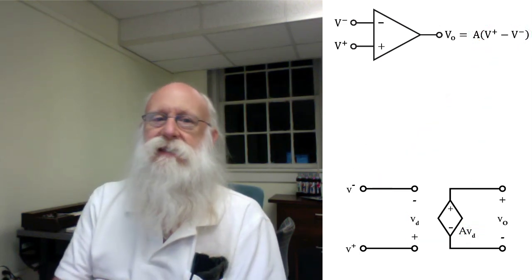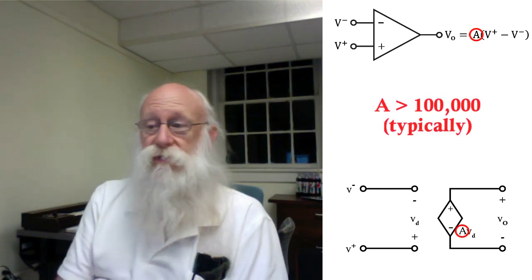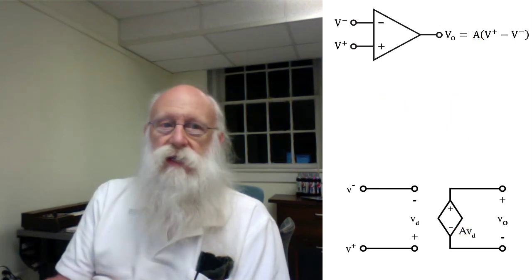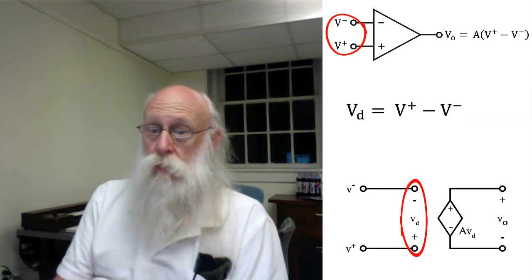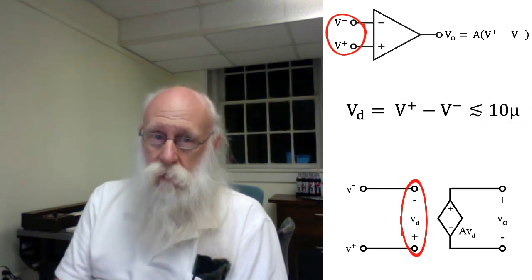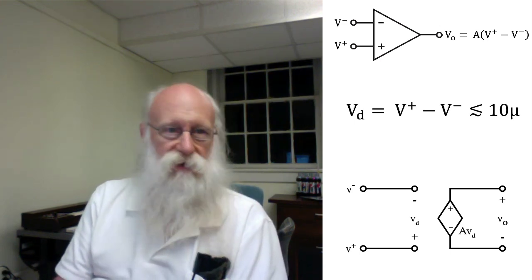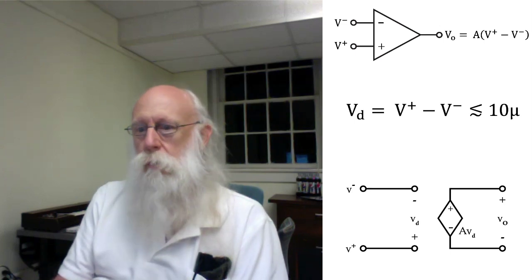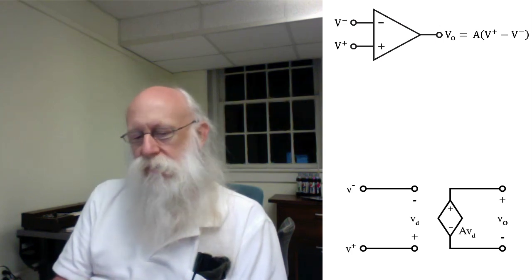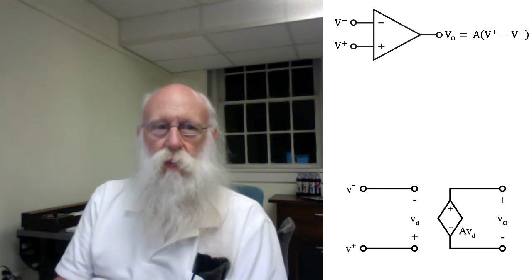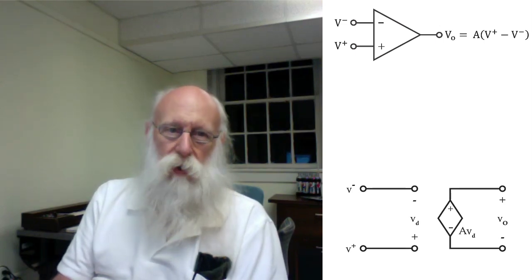The problem with this is that the amplification factor is typically in the hundreds of thousands. So this means that the difference between your two input voltages has to be really small, on the order of microvolts. This is often inconvenient at best, shall we say, and is subject to problems like serious noise issues and all of that. So it would be helpful if we could design a circuit where the difference in our two voltages of interest is not quite so small.